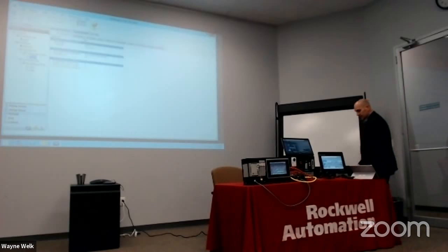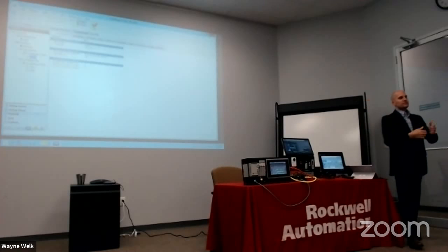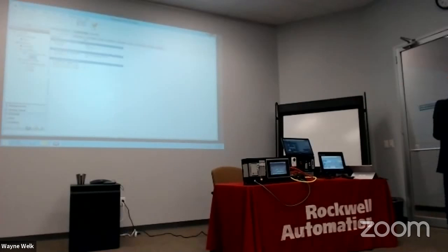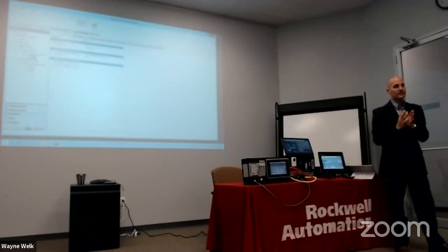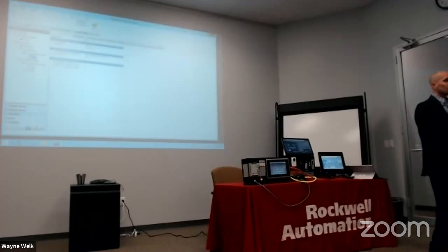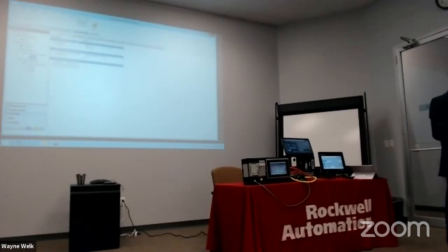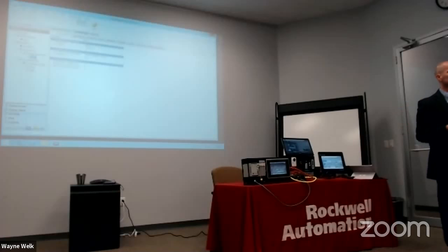So this is an Intel NUC. It's very inexpensive. The problem with it is it's got a fan. The problem with it is it's not industrial grade. The biggest problem is depending on the environment you're in. If you're in an industry that has a lot of particles in the air, it becomes not just a device. It becomes a shop vac, and it sucks in all that information. That's the problem with fan-based, non-industrial devices in these types of environments.